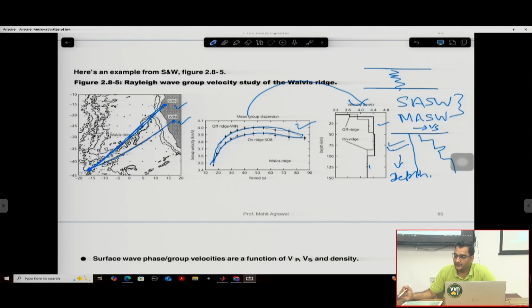And this shear wave velocity model will further give you the information about the elastic parameters of the soil that you can use for site response analysis. So in site response analysis, you might be computing the amplification factor or the transfer functions, and I think you might have studied linear site response analysis, equivalent linear site response analysis, or maybe non-linear site response analysis.